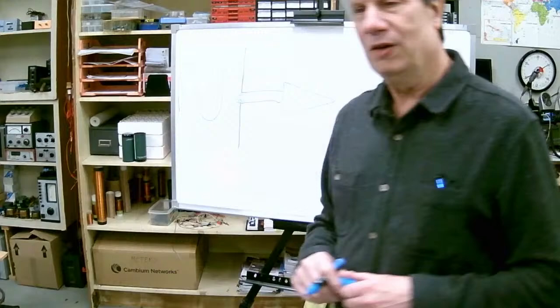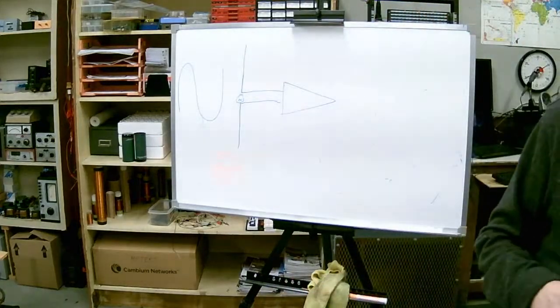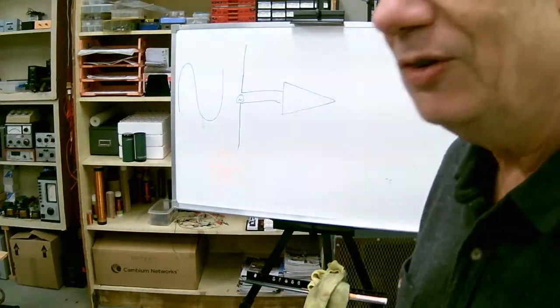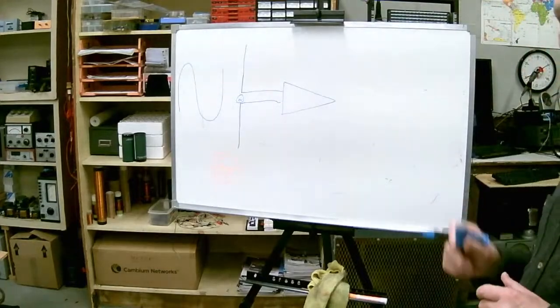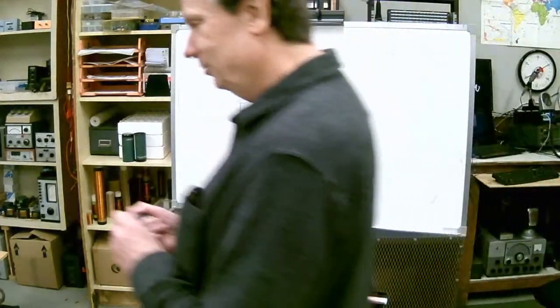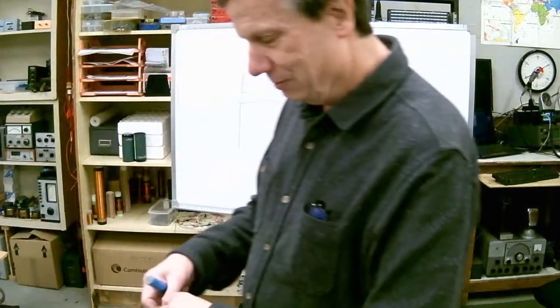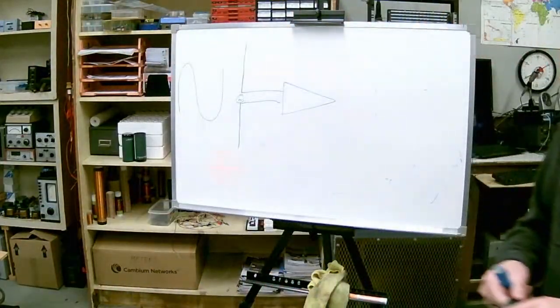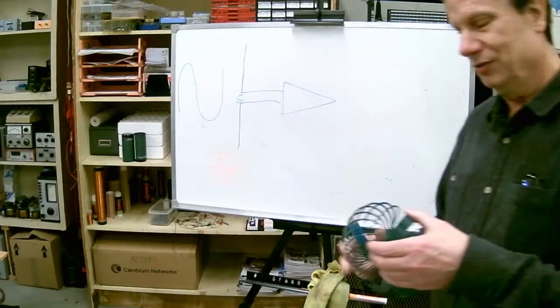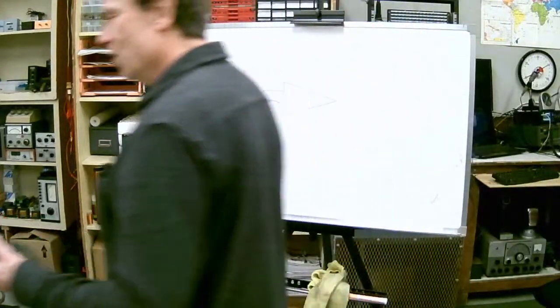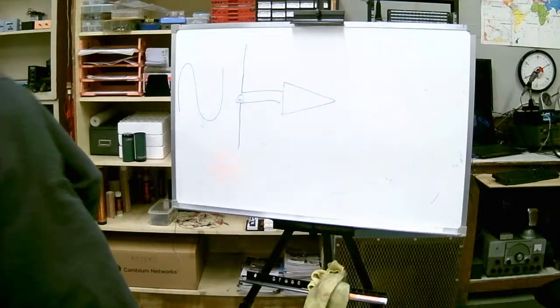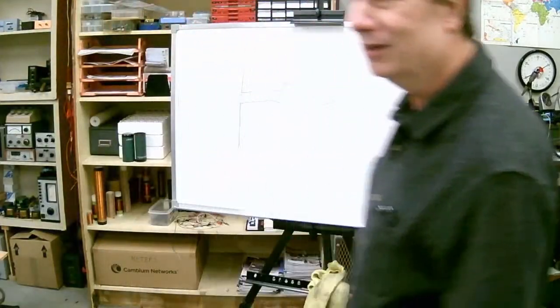The radiation resistance of a receiving dipole is exactly the same as the radiation resistance of a transmitting one. The radiation pattern is exactly the same. So our standard bagel-shaped pattern doesn't matter whether transmitting or receiving. That's what we talk about when we talk about reciprocity. It's the pattern. It doesn't care whether it's transmitting or receiving. It's a very interesting and very useful concept.